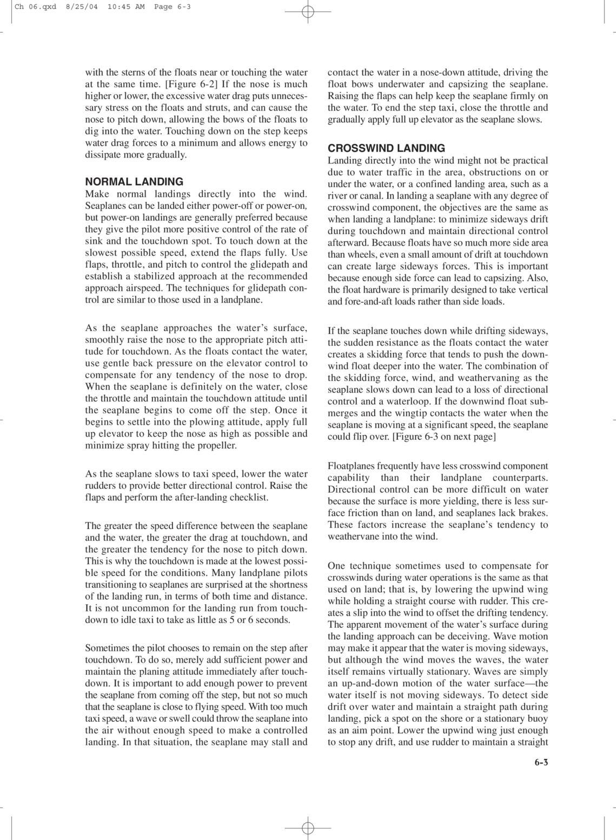As the seaplane slows to taxi speed, lower the water rudders to provide better directional control. Raise the flaps and perform the after-landing checklist. The greater the speed difference between the seaplane and the water, the greater the drag at touchdown, and the greater the tendency for the nose to pitch down.